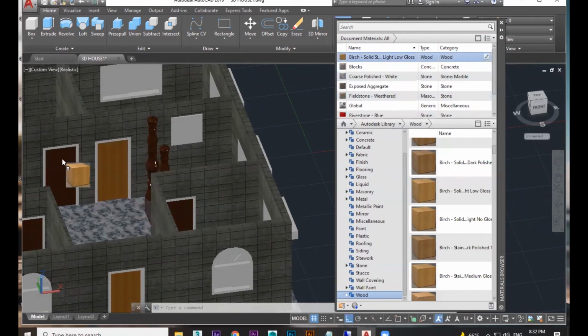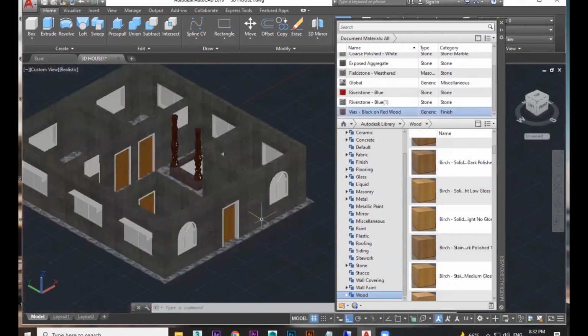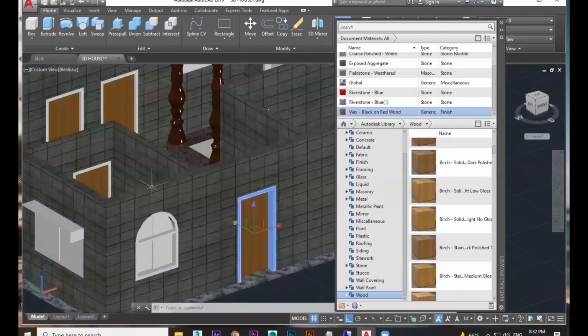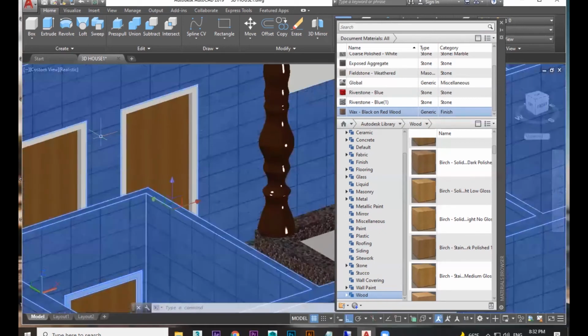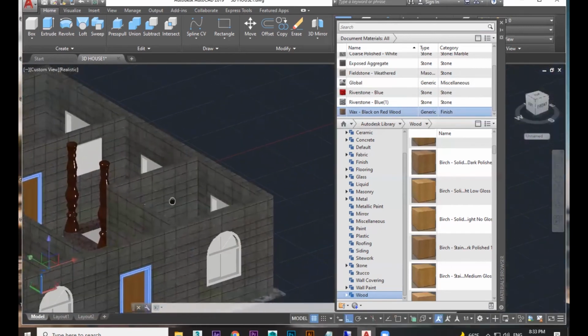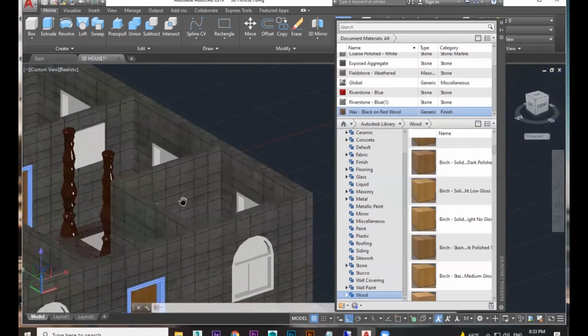This one is on the top. So select both from here. Right click, assign to selection. So everywhere that texture is going to come. I want it here on all the door frames I have selected. By mistake, if you selected other objects, hold the shift button, okay? Then click on it, and the selection will go.